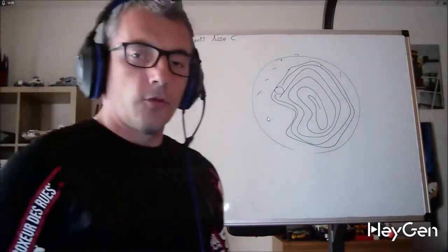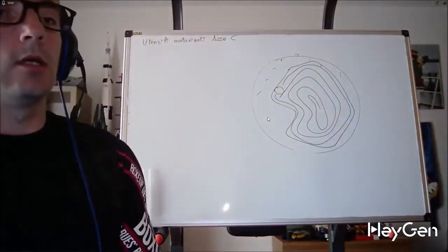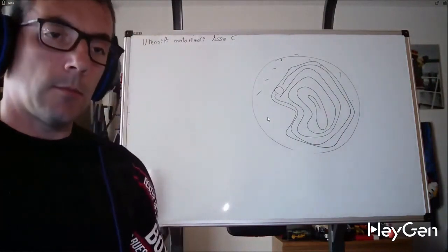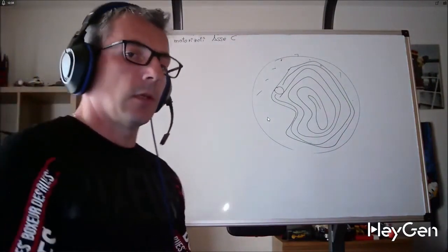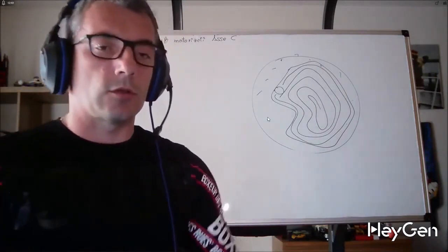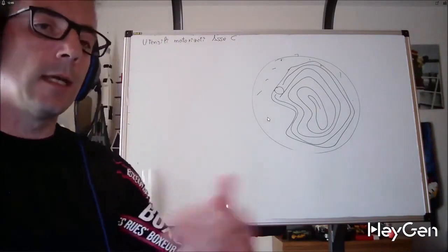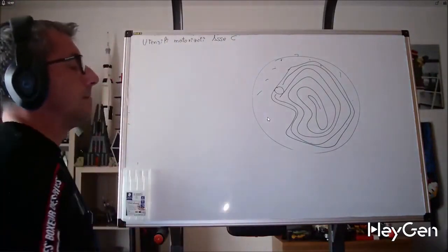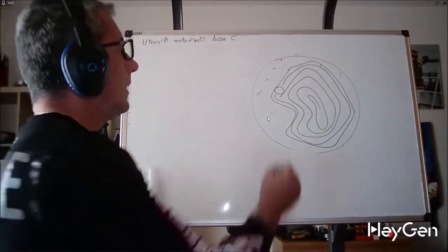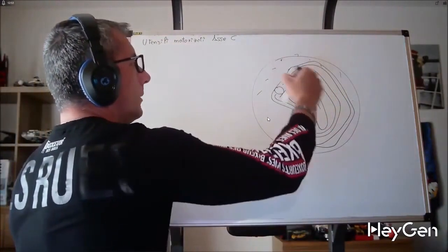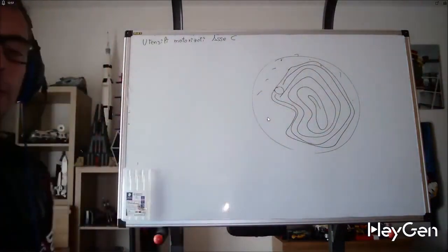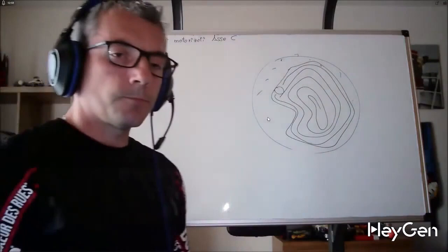If I use a conversational system like those advanced CAD-CAMs integrated into CNCs, manual guides for FANUC, Shop Turn, it still works. Each unique system has its own quirks and features. Aiden has his, Ecco has his, and Mazatrol is the queen of conversational programming, so I define the profile and then simply state whether it's a pocket or a convex shape, and it takes care of the rest.